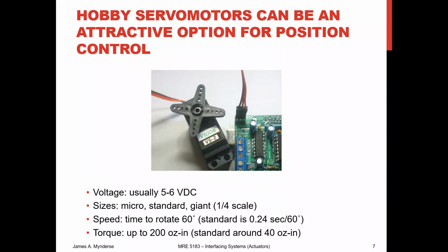One of the things that people often will try to use then is a step from a DC motor to a servo motor. So what is the difference between a DC motor and a servo motor? Well, a DC motor, you apply a voltage and it spins, which is to say that you are applying a voltage and getting speed, versus a servo motor, you are applying a supply voltage in terms of power, but you're applying some sort of signal and you're getting position. So the idea of a servo motor is just that it's a DC motor with control added to it. So you get feedback control often in form of simple PID controller, and so you are controlling position.